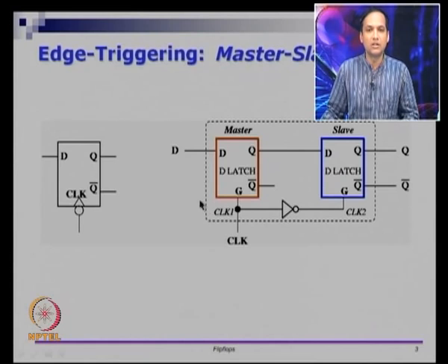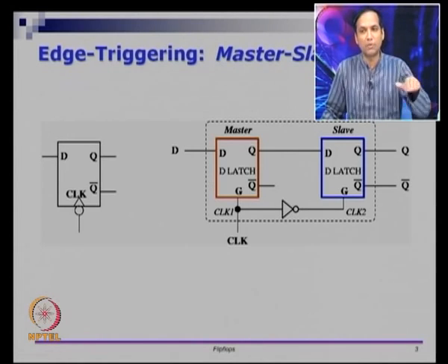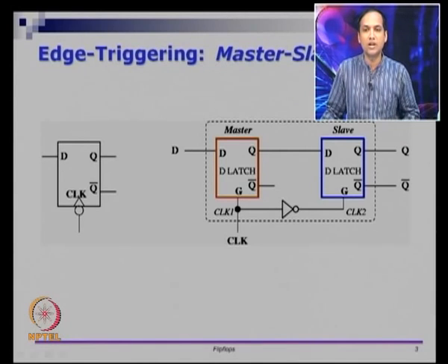Specifically, this circuit becomes what is called an edge triggered circuit. So, this circuit is not level triggered anymore. So, it is not that at a particular level of the clock D gets copied to Q. Once you connect it like this, with respect to this CLK, this D cannot be asynchronously copied to Q, which means the change in D can reflect as change in Q only at very specific time intervals, not any time that D desires to. So, there is also this bubble here, we will come to that in a little while.